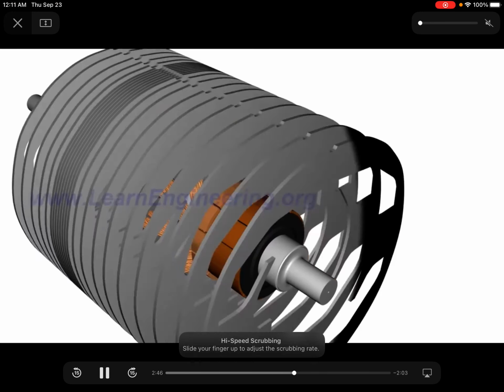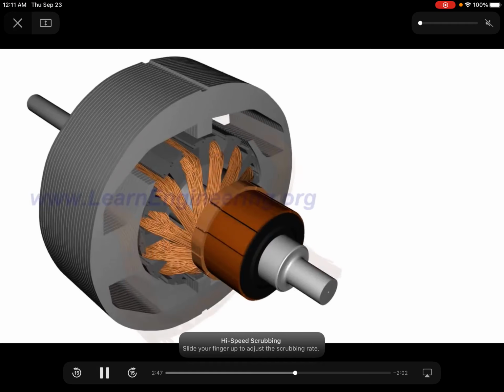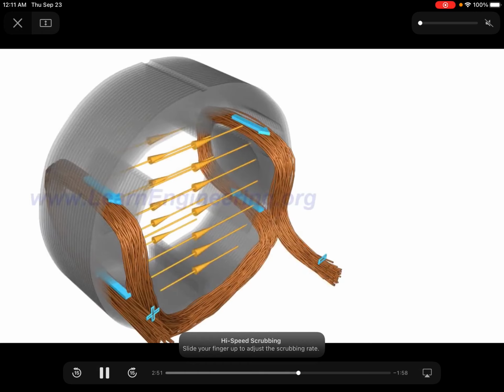Rather than just having permanent magnets, we are now placing coils around these poles, and now we have our north and south poles coming from an electromagnet rather than the simple permanent magnets we used for clarification. Actually, they can be permanent magnets, but permanent magnets tend to be a bit expensive, so we rely on them for small machines, but in larger machines, like the scale we usually talk about, we use electromagnets like this.